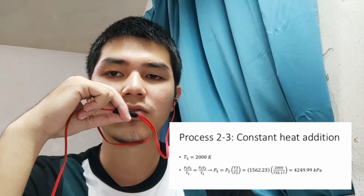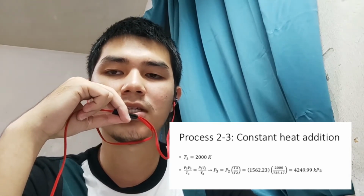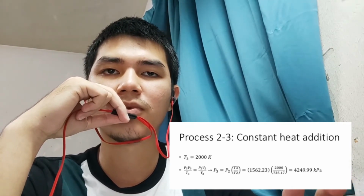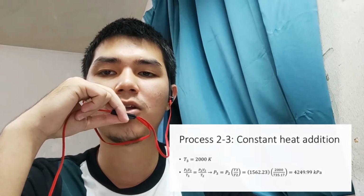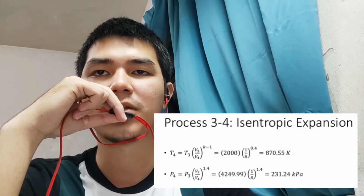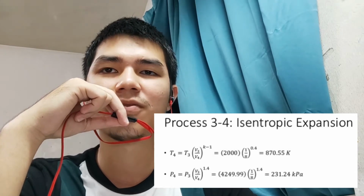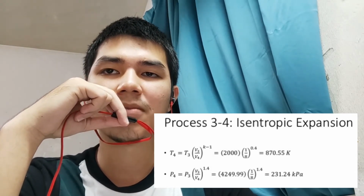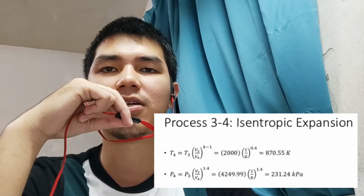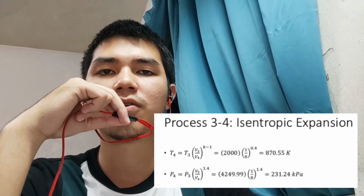Next is process 2 to 3, where constant heat addition occurs. T3 is T max, which is 2000 Kelvin, and the pressure 3 we can get by using the linear equation between point 2 and point 3, which is 4249.99 kilopascal. Last but not least, process 3 to 4, the isentropic expansion, where we can also use the formula r to the power of k minus 1 and r to the power of k, where we get T4 as 870.55 Kelvin and pressure 4 as 231.24 kilopascal.